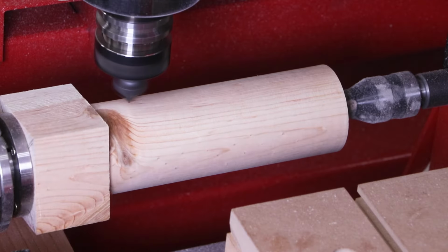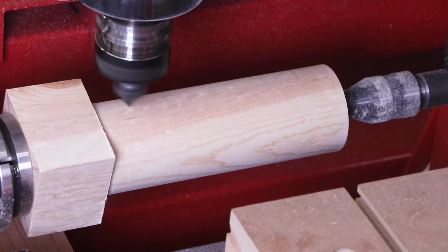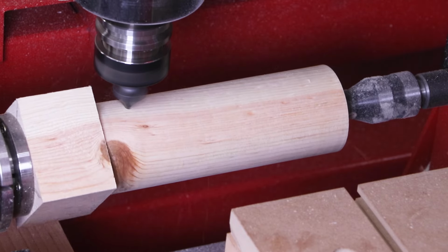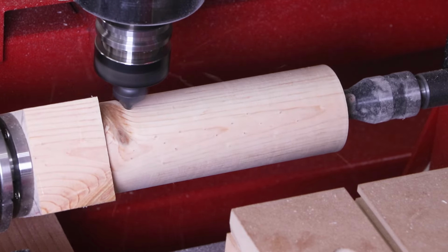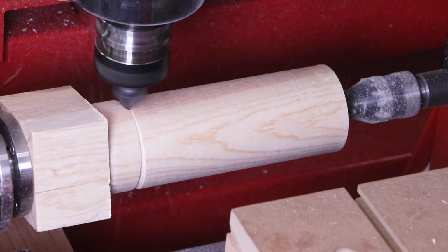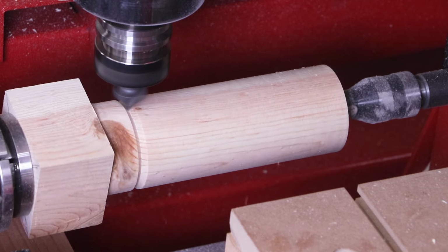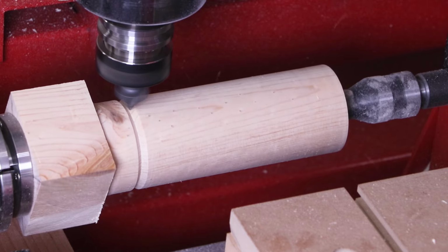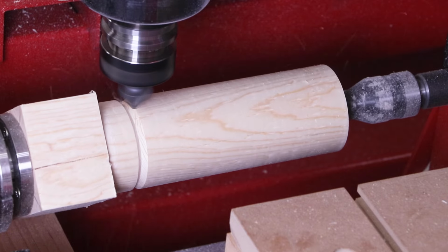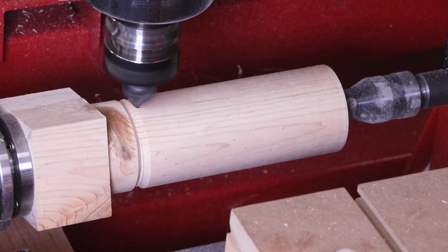To begin, the cutter comes all the way down to that section diameter of 2.5 inches to start a controlled plunge into the material while rotating the stock. This is going to be doing that termination default, where again, it turns the profile of this cutter around the circumference of the part before it starts the actual threading process. Once it's applied that 360 degrees around the circumference, the cutter immediately starts traveling down the length of the stock, and it's traveling 1/4 inch per rotation. That's 1/4 inch pitch, giving us 4 threads per inch.